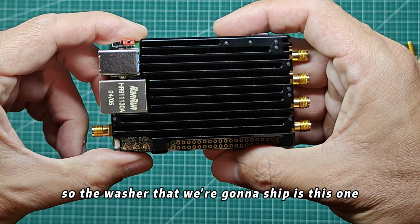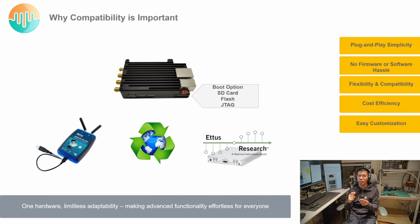The boot option is trying to tell us that you're able to boot from SD card, you are able to boot from the flash, and you are able to boot from JTAG. So you just need to change the jumper on the pin. The different sides will represent different ways of booting Signal SDR Pro. And remember, we have an SD card slot, right? Which is right over here. So if you put your jumper here, put in an SD card, and compile a firmware, name it boot.bin, put it over here, it will be able to boot your firmware.